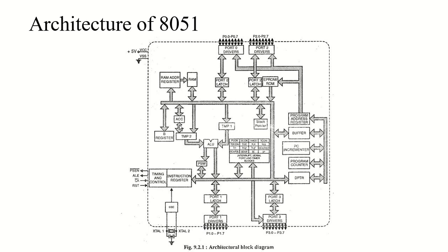and it holds the source operand and receives the results of arithmetic operations including addition, subtraction, integer multiplication, division, boolean multiplication, any other boolean manipulation, anything, right? It serves almost the same purpose that it used to serve back in 8085. It is also used for data transfer between the 8051 and any external memory as well.